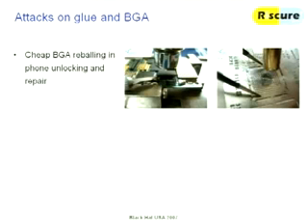These pictures were taken from a site in the phone unlocking business. These days, the mobile phone manufacturers have turned to the same kinds of protections, making chips that are glued to the board, that are difficult to replace, but they can be replaced. People just practice, and you can do this with just a couple of bucks of equipment. This is not expensive BGA equipment with XY tables and stuff like that. It's just by hand, and you can re-ball, and we use the same techniques also, because it's easy, it's cheap, and it's fast.